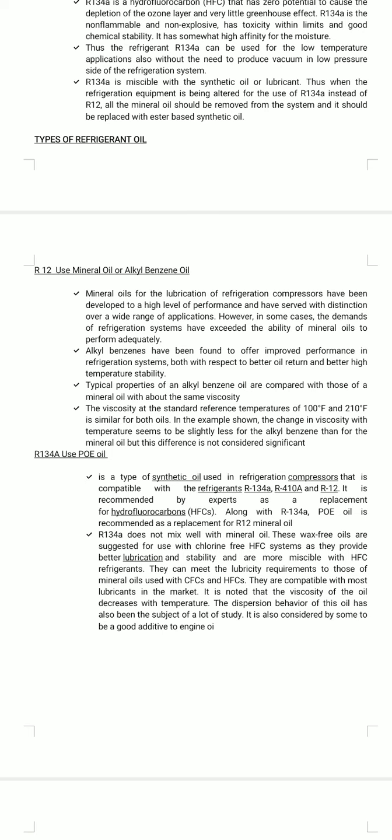The viscosity at the standard reference temperature of 100 degree Fahrenheit and 210 degree Fahrenheit is similar for both oils. In the example shown, the change in viscosity with temperature seems to be slightly less for the alkyl benzene than the mineral oil, but this difference is not considered significant.